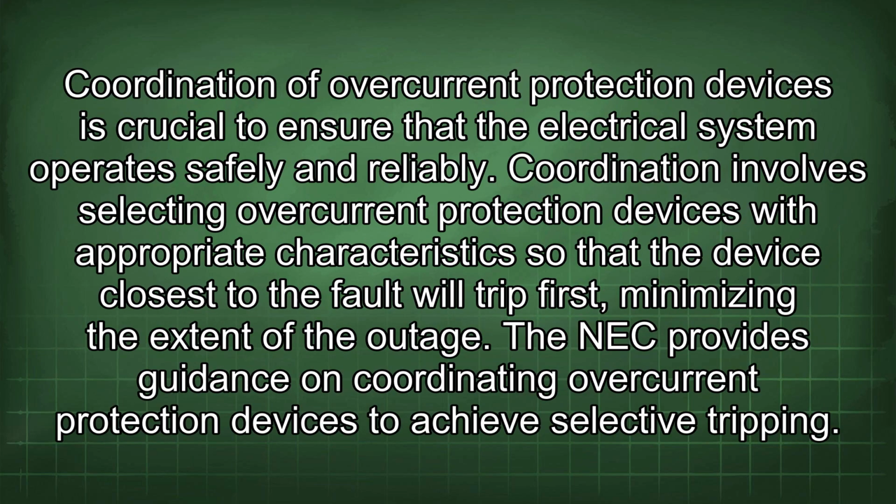Coordination of overcurrent protection devices is crucial to ensure that the electrical system operates safely and reliably. Coordination involves selecting overcurrent protection devices with appropriate characteristics so that the device closest to the fault will trip first, minimizing the extent of the outage. The NEC provides guidance on coordinating overcurrent protection devices to achieve selective tripping.